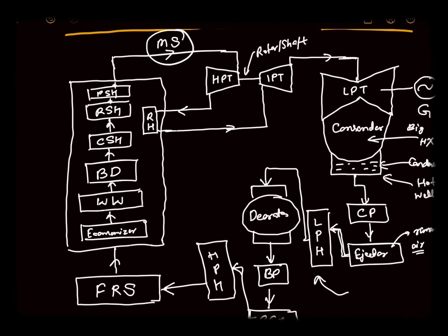So here we have used different types of superheaters. First is the convective superheater. In the convective superheater, the steam formed is superheated with the help of the gases released from the boiler. And in the radiative superheater, the further superheated steam is warmed with the help of the radiation emitted from the boiler.